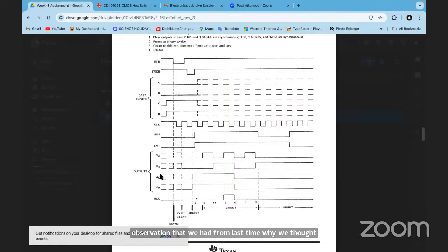Now what you do is you take your ADALM kit, channel A, channel B, and configure both as a signal generator to generate the same square wave. Short the two outputs. Then give channel A, channel B to your counter now. You will see that the counting is actually better. So there are certain counting patterns that require more current than the others. So this will now count 0, 1, 2 or something, and then it will start failing. Something like that happened.